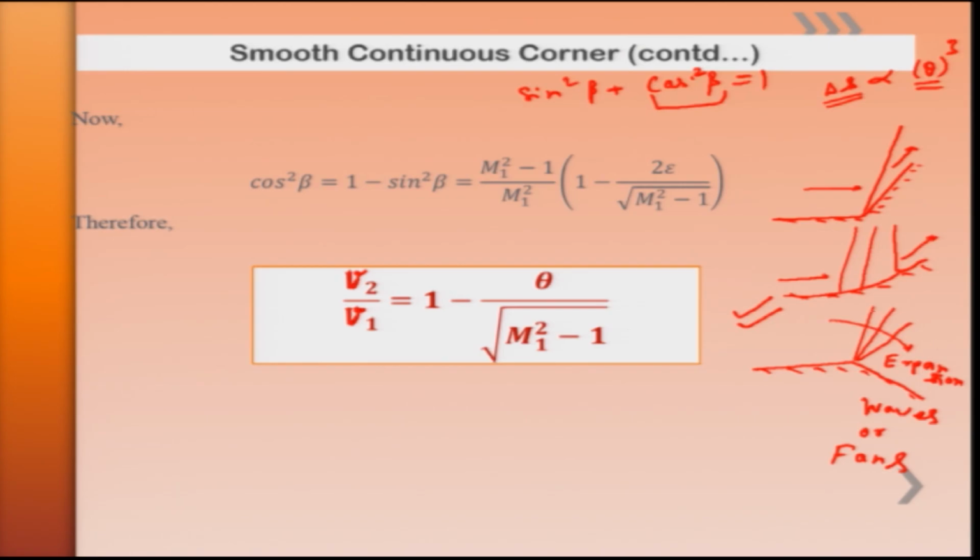For example, when there is a sudden change in the flow deflection angle, such as shown here, where the surface geometry is suddenly changing to cause the flow deflection, then at this particular point where all the expansion fans are meeting, let us say P, which is nothing but our vertex, the waves gain sufficient strength, and hence whatever flow passes over this vertex will no more be isentropic.